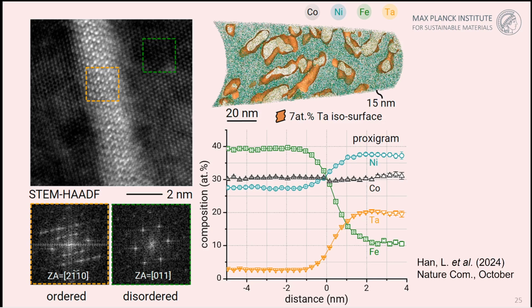Another very recent approach was also to not just create nanoparticles and tune them in terms of the dispersion and size, but also change the shape of these nanoparticles, as you see here in the atom probe analysis. And you see here also from the STEM HAADF image that you can tune by precipitating some of these L12 particles along the dislocation course, very elongated shapes of these particles, which again has big advantages for very effectively changing the mechanical properties while not impeding the motion of the domain walls.